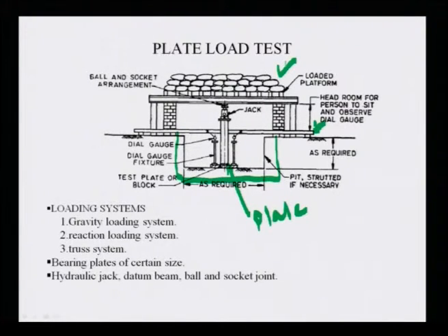What will happen? Whatever pressure I apply to the hydraulic jack, it will try to uplift the reaction beam. If a proper loading platform has been made with loading systems, it will not allow this reaction frame to be pushed from outside, because each action has an equal and opposite reaction. Once this reaction is applied here, the plate will settle with the opposite action.